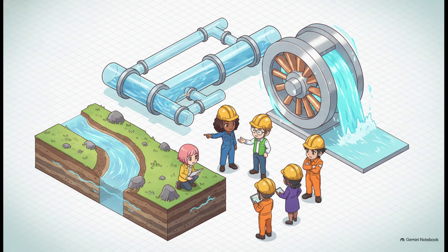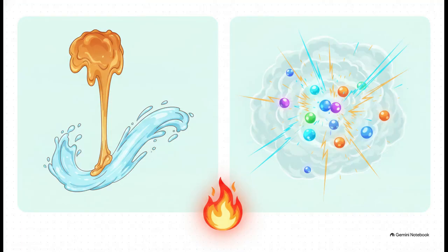It is literally everywhere. But hey, there is a crucial environmental caveat you must always keep in mind when engineering. These fluid properties are highly temperature sensitive, and they don't all behave the same way. For liquids, as you add thermal energy and increase the temperature, the fluid flows much more easily, meaning its viscosity decreases. But fascinatingly, for gases, the exact opposite is true. As a gas heats up, its molecules start colliding much more violently with each other. All that chaotic bouncing around causes the gas to actually thicken and increase its internal resistance to flow. No way, right? But it's true.